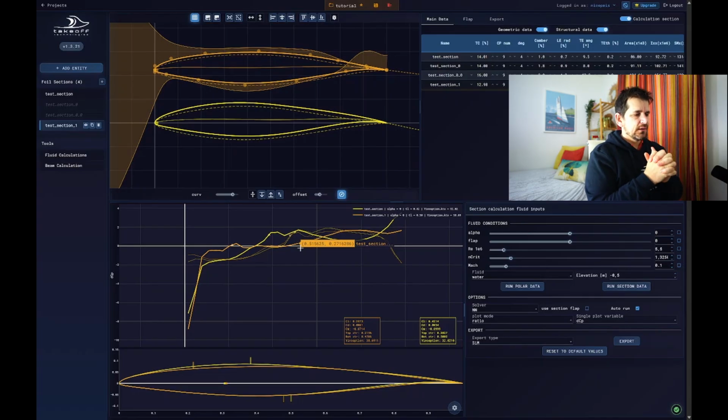And we know that Airfoil doesn't capture the separation drag well. I mean, it's totally off. So the safest thing to do in Airfoil is to try to minimize the risk of separation. So the gradient could be a good way of checking this separation.